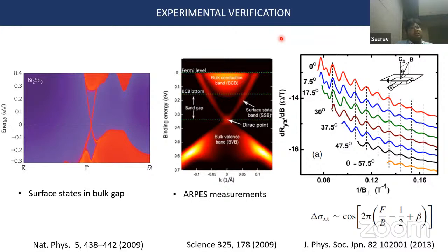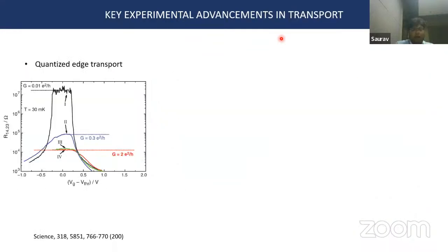So initially, research focused on materials like bismuth selenide and antimony telluride, but these materials all have their own defects. Some are N-type, another material is P-type. So you combine these two materials, both bismuth selenide and antimony telluride, let's say, and you achieve what is called a compensated state. So N and P separately are non-zero, but N plus P is zero, to achieve less bulk conduction in these cases. And of course, a lot of advancements have happened in molecular beam epitaxy.